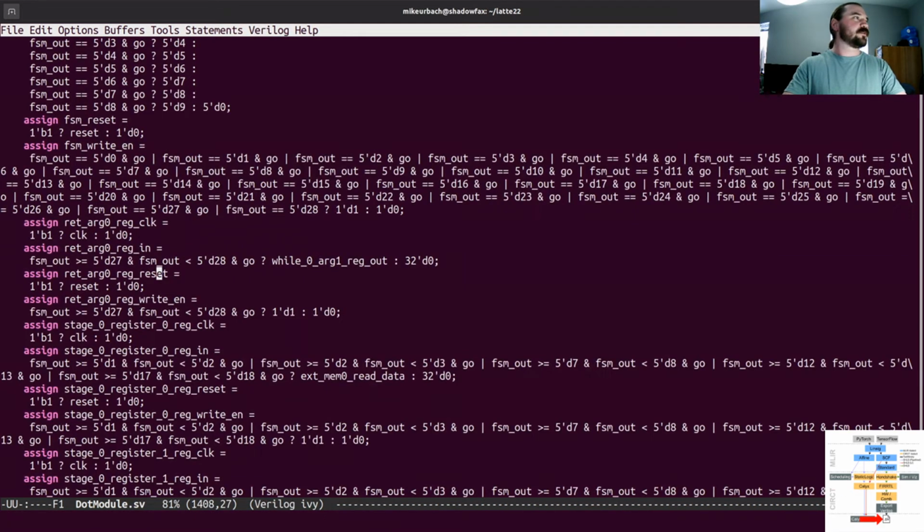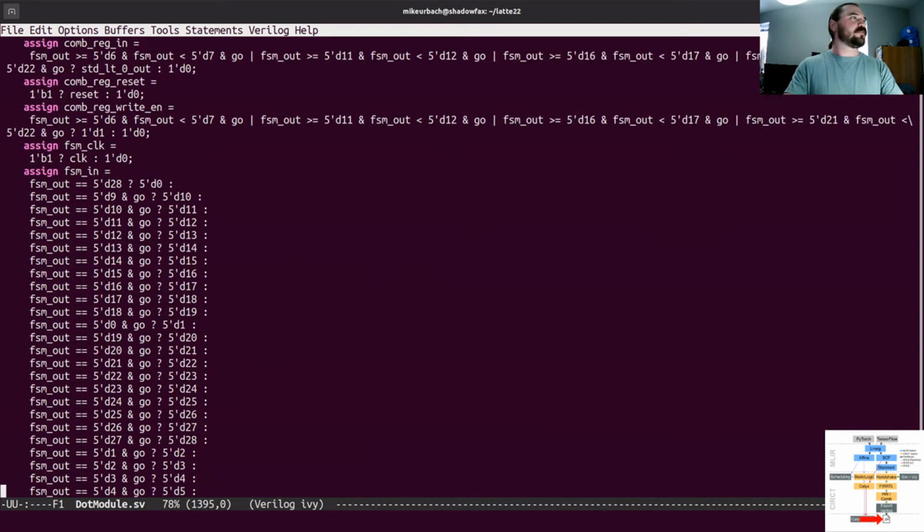If we look at the generated Verilog, we can take a look at the finite state machine and see that now it just transitions directly on the correct cycle. There's no more latency insensitivity. So we used more high-level information, and that helped us generate better hardware.